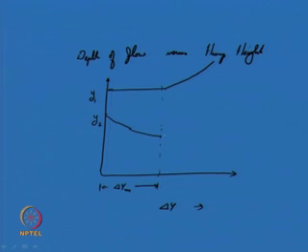Here, this is your critical depth, and from here the section 2 will maintain the critical flow condition itself, whereas at section 1 the elevation of water will increase. This is how you can interpret the following graph, or you can easily draw them. I would like you to do it as an assignment.